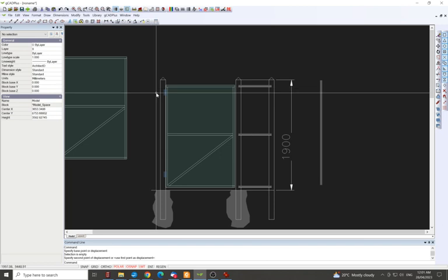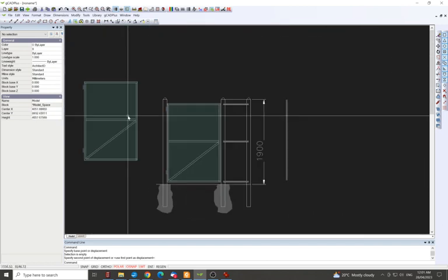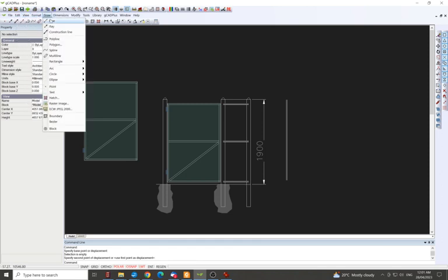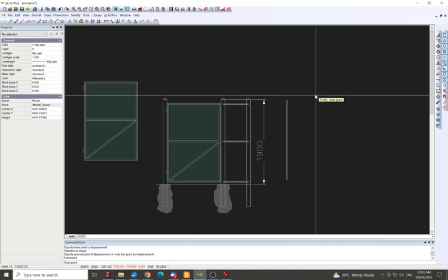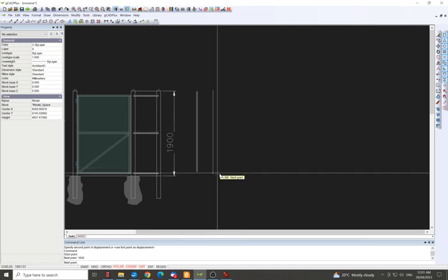So really what I need is, yeah, I made that the wrong size, but don't worry about it. I'll fix it up later. For intended purposes of building the gate, it doesn't matter. So we'll get 1850. I need them to be 1800 actually, because the bits of timber I'm buying, they're 5400, so that divides to 1800, and I don't want to waste timber.